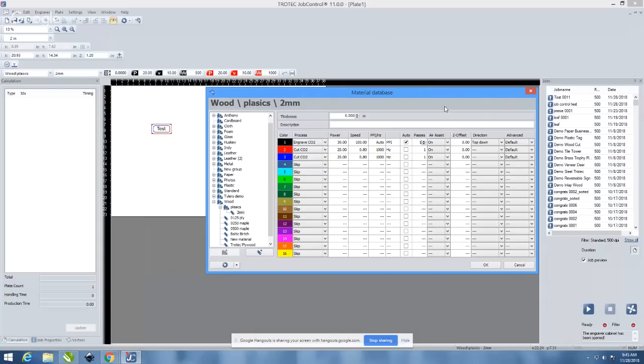Yeah, some people use, like, our textured material has a very, very thick top layer. So sure, you could do it in one pass with lots of power, but then you'll have a lot of that residue, especially if you don't have the original masking on. So a lot of people would use lower power with 2 or 3 passes. Again, it just depends on the material and what you're doing. Same thing with wood. You're not looking for a lot of that residue, especially if you don't have a masking on it. You may want to do lower power in multiple passes.